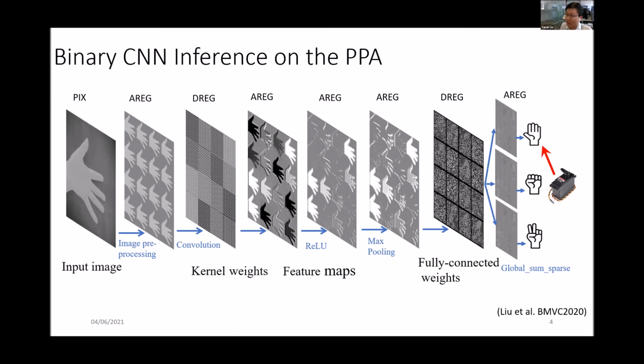Another solution is to combine sequential and parallel implementation of the convolution. For example, if we need 32 kernel filters, we can use this single image, but with 2 digital registers storing those kernel filters, and perform convolution twice. In that case, we can get 32 filter maps.